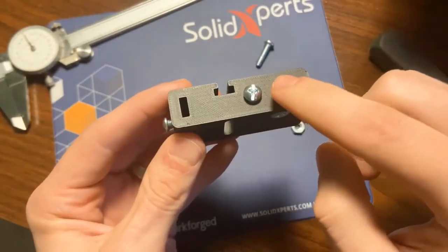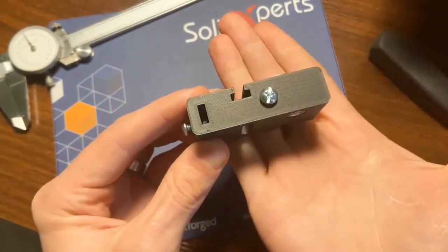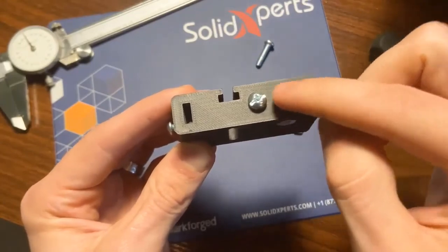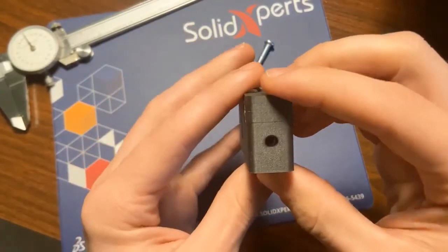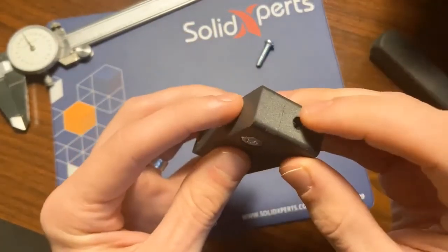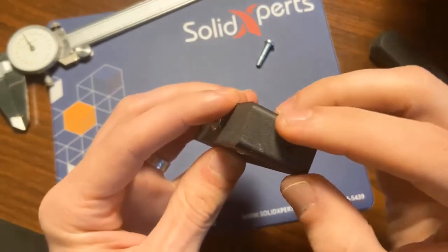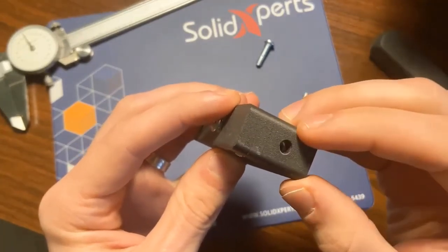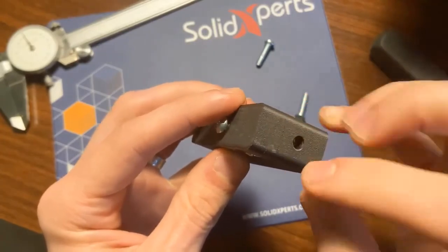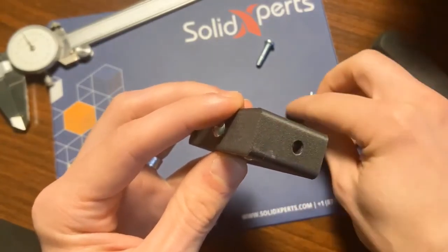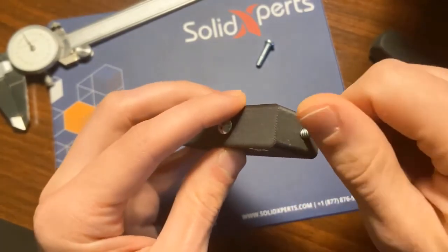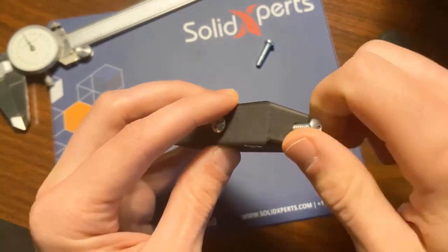Now this is a horizontal example. So this was printed upright like this, and we had a small spacer put on top. As I mentioned before, there are options like using the bow tie. So again, we can have a vertical application, insert the hexagon nut in a hexagon channel, add the bow tie on top, and again, another nice smooth flush print. And again, another fastener can go in there and make contact with the hex nut.